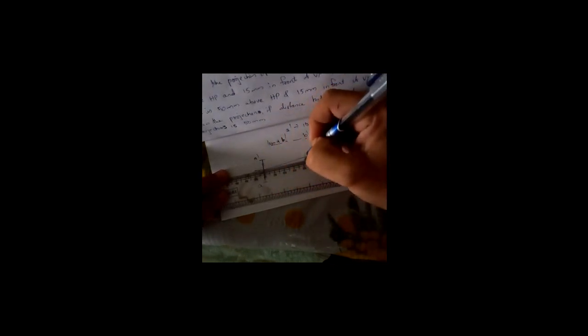Distance between end projectors means the distance between the end points. Our line is AB, that is, the distance between the projector of A and the projector of B. Projector of A means A dash and A, projector of B means B dash and B. That is the distance between A dash A and B dash B, measured parallel to the XY line. So the distance between A dash A and B dash B is given. Distance between end projectors is 50 mm, measured parallel to the XY line, meaning you measure on the XY line itself. So on the XY line, from here to here, how much to take? Take 50 mm on the XY line. So by scale, take 50 mm on the XY line from A dash,